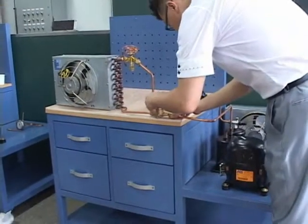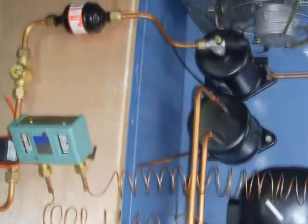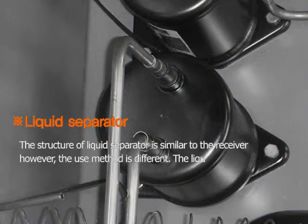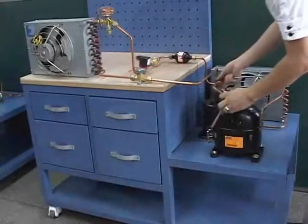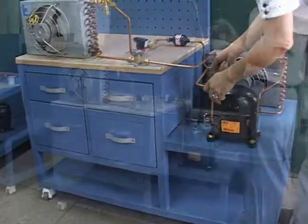Next, we fix the liquid separator aligned to the table hole. The structure of the liquid separator is similar to the receiver. However, the use method is different. The liquid separator should receive only gas, different from the receiver. Therefore, in and out are separated to charge the upper area gas only. It protects the compressor from wet compression. The piping of evaporator discharge and compressor charge will be completed.